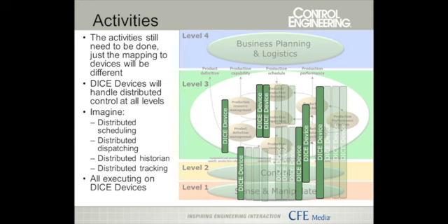So a single device might be performing the sensing and manipulation of the process. It might be performing the basic control because it's going to be executing some of the control strategy, the PID control, the on-off control, the model-based control, the advanced process control. But it may also be doing the procedural control, the workflow controls that exist for dispatching and scheduling.